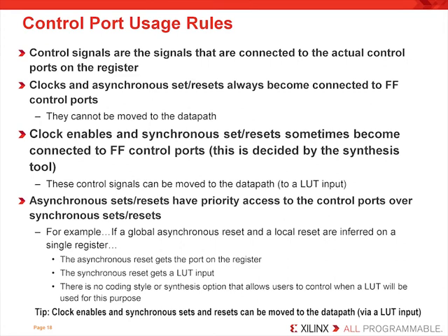So let's take a second and review all the control port usage rules we have covered so far. Control signals are the signals that are connected to the actual control ports on your register. Clocks and asynchronous sets and resets always become connected to the flip-flop control ports. That's because they can't be moved to the data path.